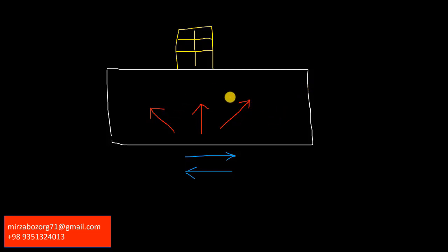So when the simulation is conducted, if these waves cannot go out from the boundaries, then they will be reflected in the ground, and it means that the earthquake is magnified, okay? But this is unrealistic. This is not correct. In reality, they will go outside of the ground in other regions too, and nothing remains here.